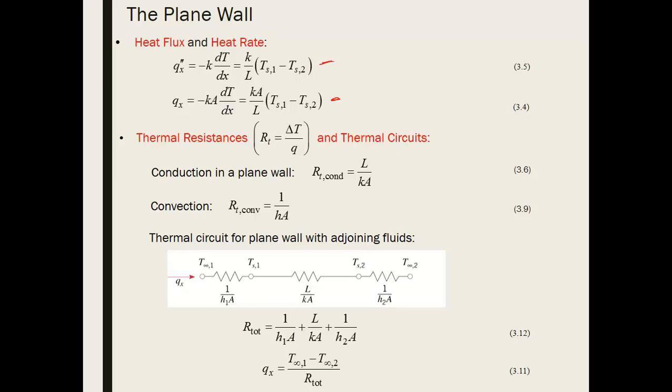The heat flux can just be defined by taking a delta of the temperatures divided by L, because the temperature profile is going to be just a straight line, as we solved before. So you're just trying to get the slope of that line. The derivative of this line ends up being equal through the whole wall. So in these conditions, the math gets even simpler. You just need this very simple algebraic equation to find flux or heat rate through a plane wall.